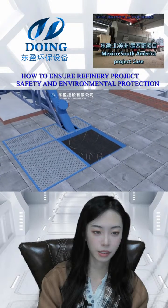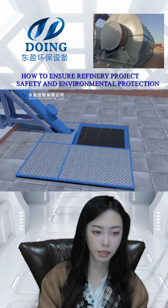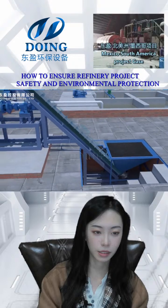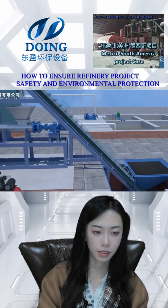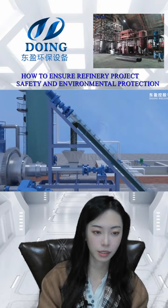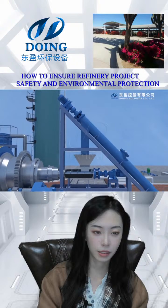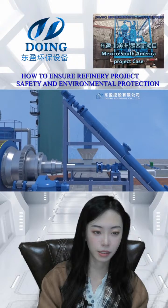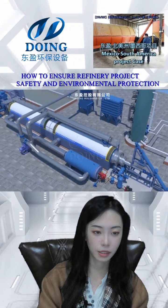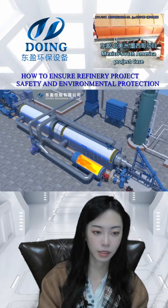And other technique, like the batch type, we need to ensure that we discharge the carbon black at a normal temperature. But the fully continuous one can discharge the carbon black at a high temperature, so they don't need to cool down the reactor to have a safe environment. This is why it has a much higher efficiency. It's a kind of different.